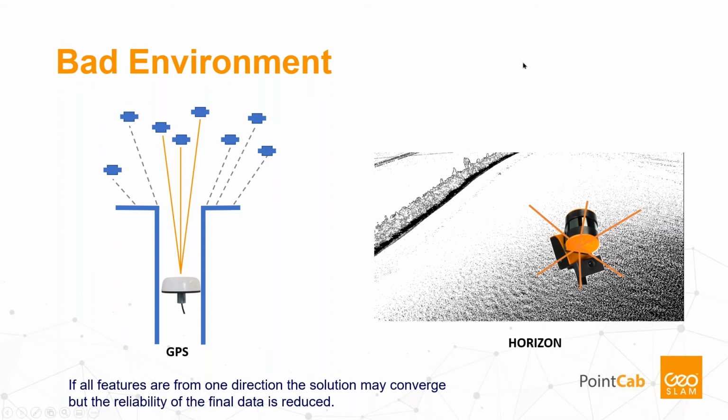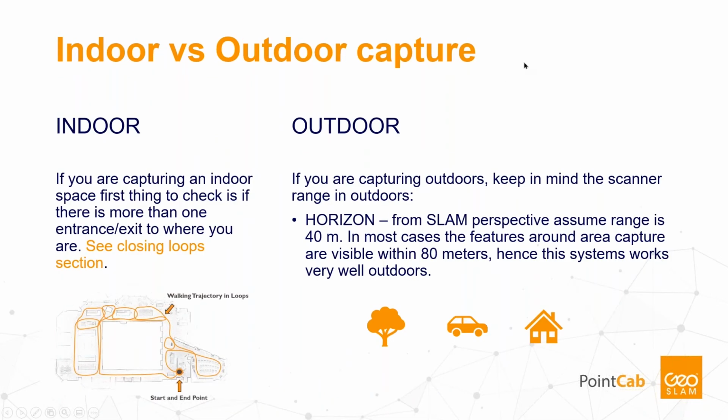So moving to the scanning practice. What is the best capture practice for indoors and outdoors? For indoors, you should plan where to start a scan and ideally be able to approach this start location from the end, from a different direction, and perhaps also plan to open doors that will make it easier to loop in each room.